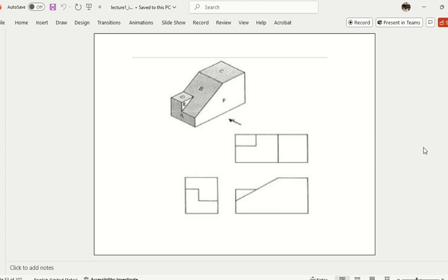Third angle, okay? Because the top view is on the top. So, you can see the inclined as well. When you're looking from the side, you see the inclined. And when you look from the side, you see this L shape, and above this L shape, you have another L shape as well. So, two L shapes.